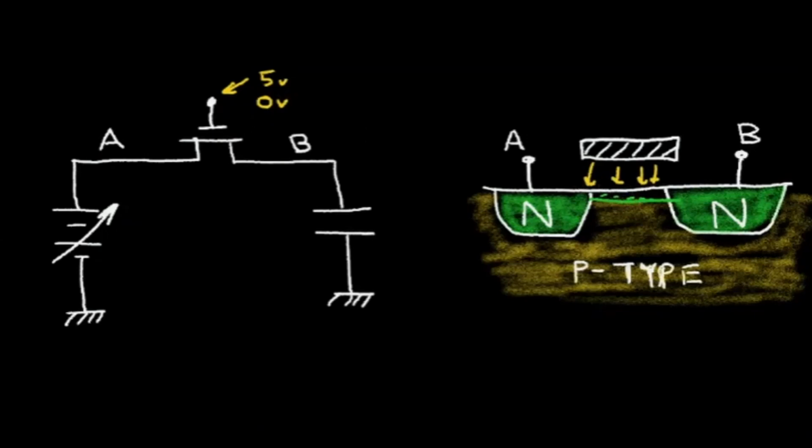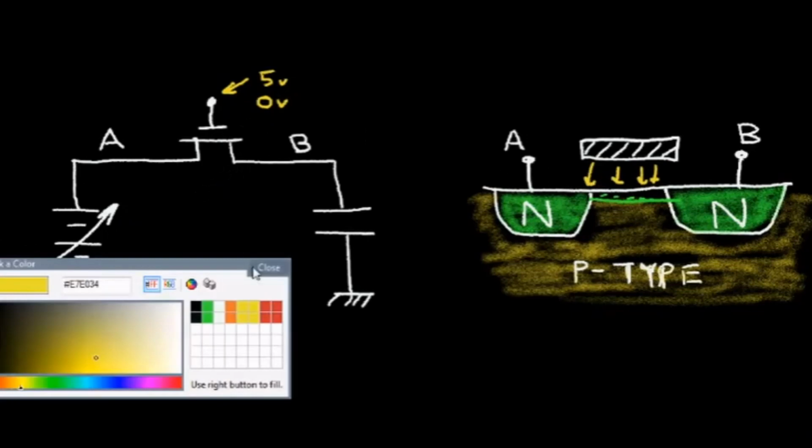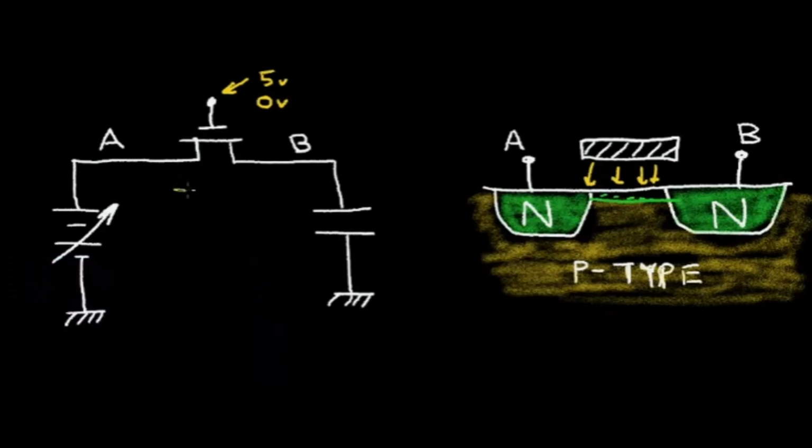So in the case of a MOSFET, it is a rather resistive device. So I don't have to worry about a large surge current in this capacitor when I close the MOSFET switch, or put the gate voltage at a high voltage. So let's see how well this MOSFET can work.